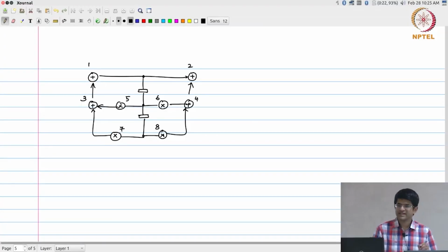So first things first, before we even try to change the structure of this graph, the first thing that we probably should do is try and get an estimate of how much I can potentially improve it. Is there an iteration period bound that I need to be concerned about in the first place? Because right now I have seen that my critical path is 5 time units. I was thinking of reducing it to 4 so that I can get a 100% hardware utilization efficiency, possibly.